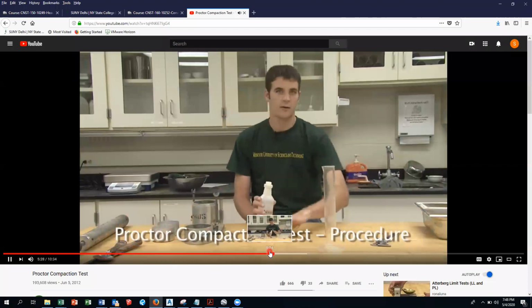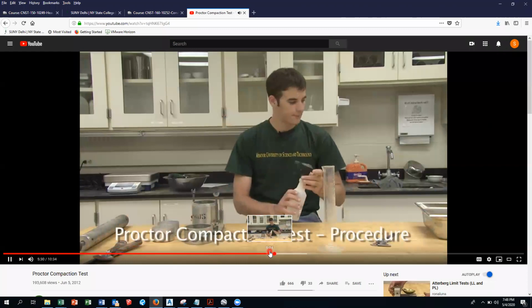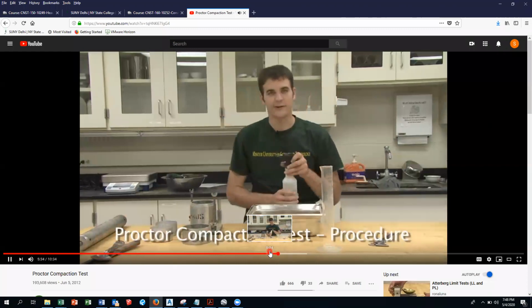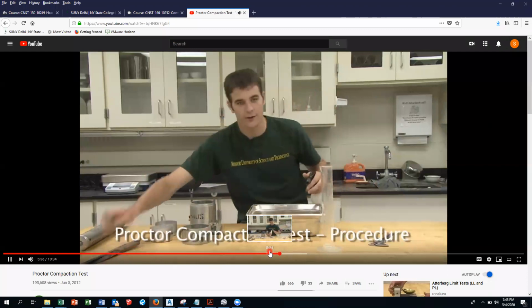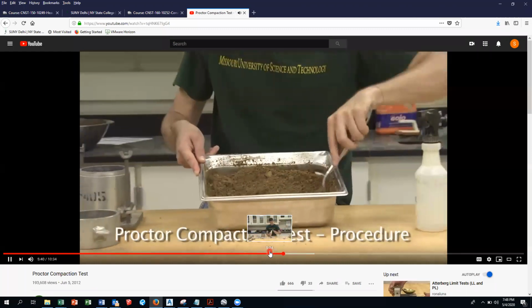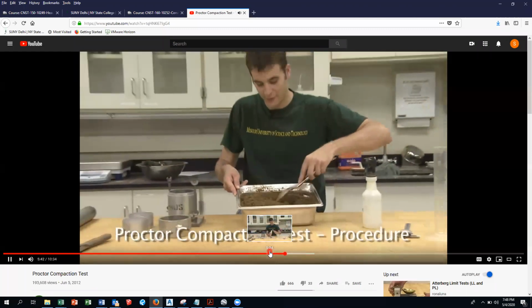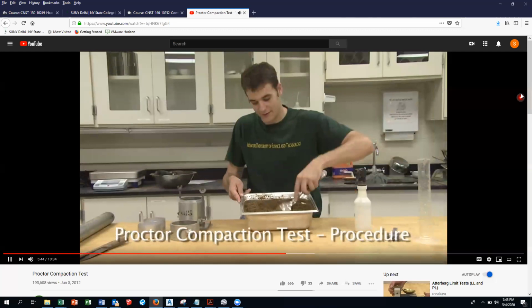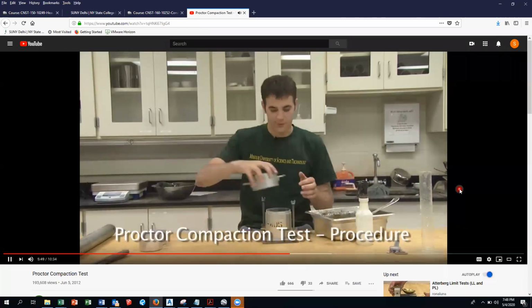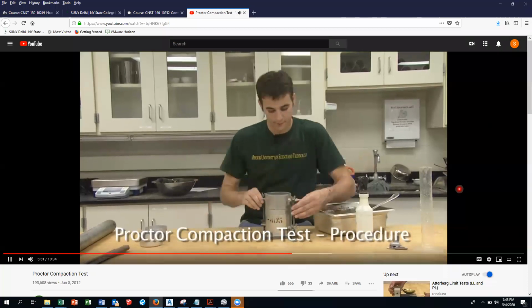So now he's going to add some water to the sample using the spray bottle, and start mixing the soil until it becomes a uniform color and consistency. When all the water is gone and the soil has been mixed to an even and uniform consistency, it is time to place the soil in the Proctor compaction mold. Start by placing the collar back on the Proctor mold.